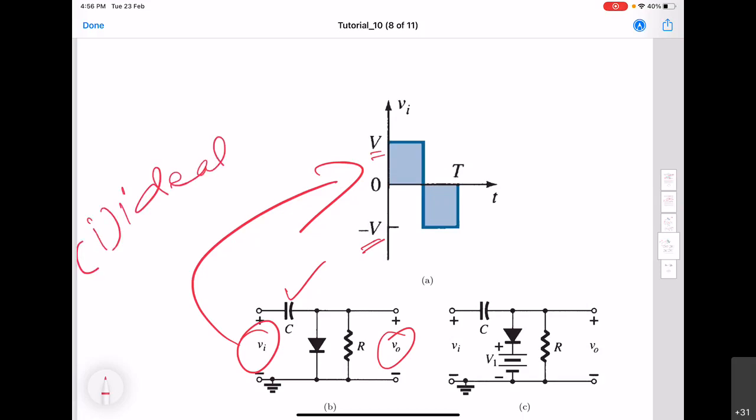So this is one thing you have to keep in mind. Second is that this time period is quite small compared with the time constant. So the time period is significantly small. That means there will be hardly any opportunity for the capacitor to get discharged if an RC circuit gets formed, which we will see actually invariably gets formed also.